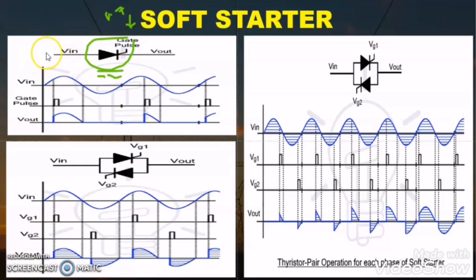It is around 0.7 volt. The input voltage can be 450 volt, any voltage, which will be written on the thyristor itself, but it will be very high. For example, if 450 volt is the input voltage, the thyristor will not pass this 450 volt until we give this 0.7 volt at the gate terminal. So at the moment we give a gate pulse, the thyristor acts like a closed switch and passes the voltage, and before the pulse it will not allow any current to pass through it.